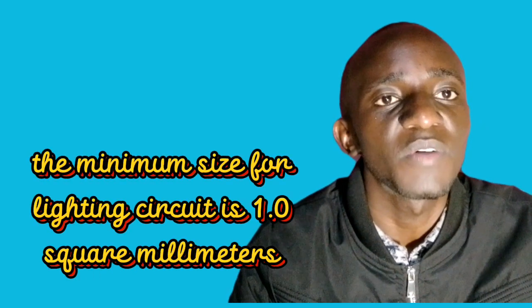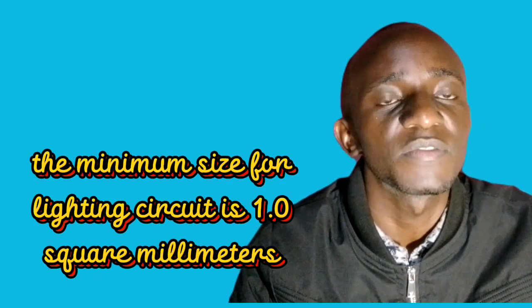These are IE regulations that are required when doing an installation in a lighting circuit. Number 1, the minimum cable size for a lighting circuit should be 1.0 or 1.5, and this is to ensure that when the cable is drawing current, it is drawing at minimum voltage drop. We're going to look at the procedure of selecting cables, and we'll see how the size of cable affects the voltage drop.